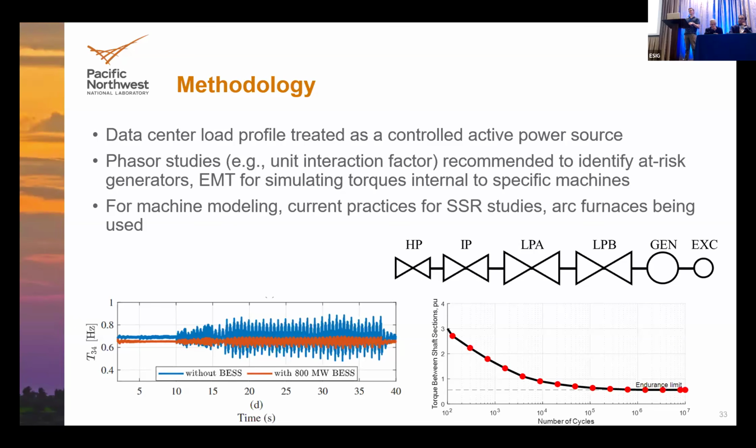However, because these fatigue curves weren't really developed with this application in mind, we don't know how good the precision is up at this upper limit. There's a little bit of data out there that goes up to maybe 10 to the 9 or 10 to the 10 cycles that suggests the withstands could be a bit lower. So a lot of people conservatively are going to maybe a little less than half of the endurance limit as kind of a target value.